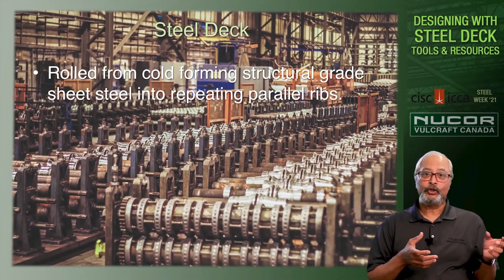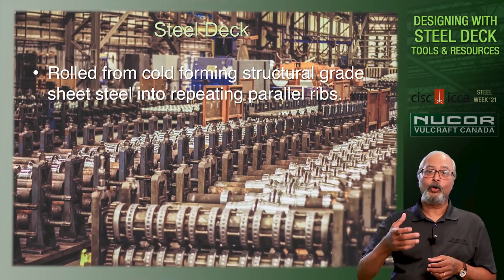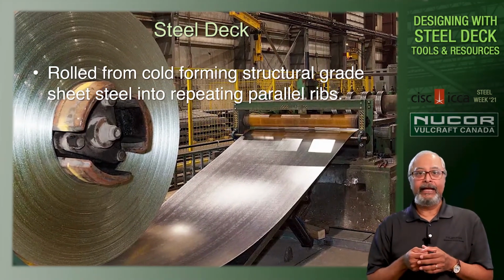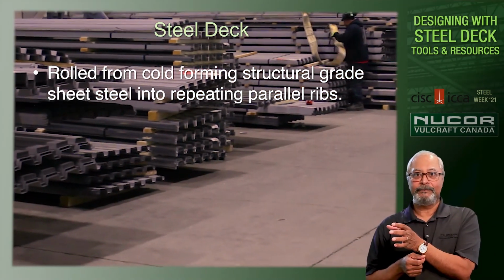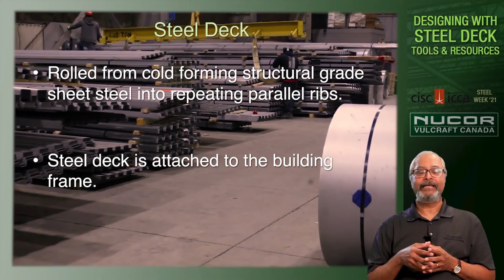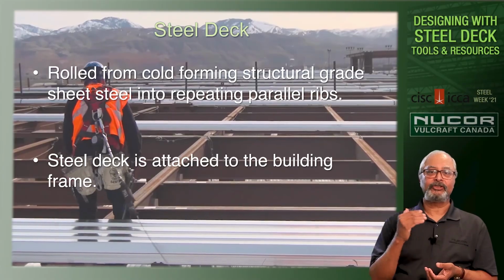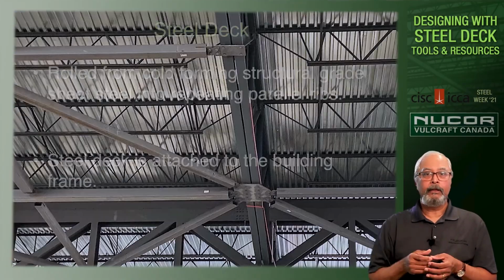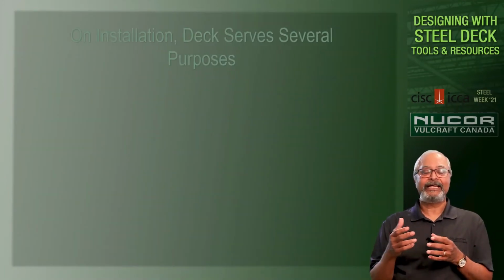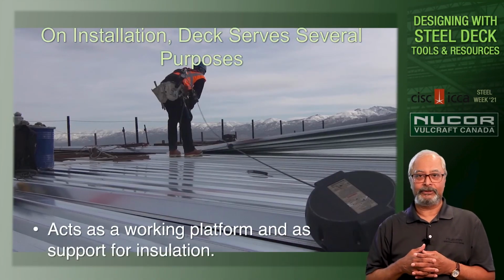Steel deck is rolled by cold forming structural grade sheet steel into parallel ribs. In construction, a steel deck is normally attached to the top of the structural building frame. And after construction, steel deck serves several purposes.